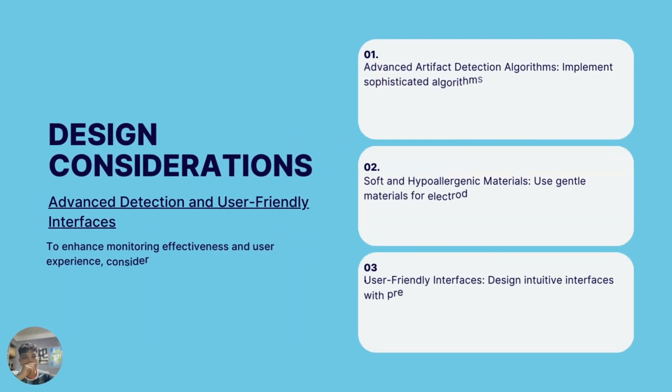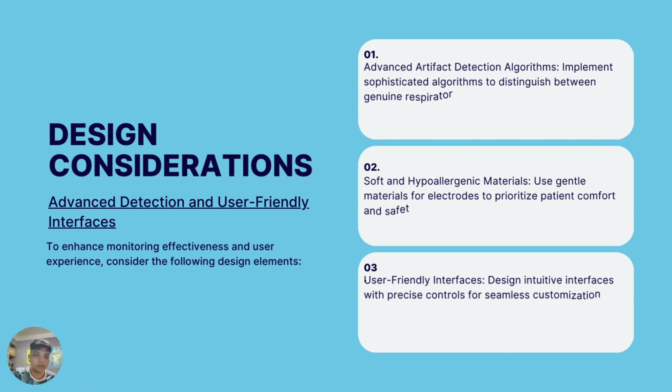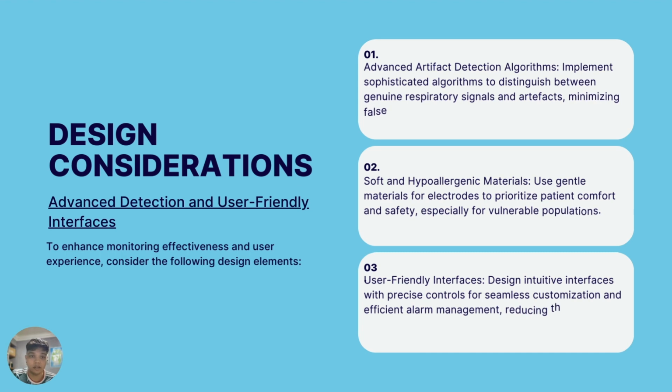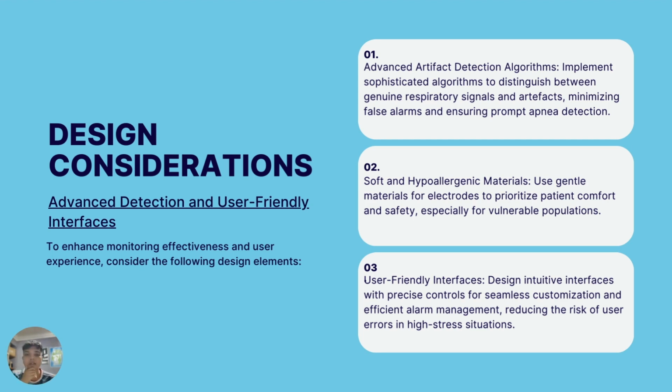Next, what are some design considerations? First off, designing apnea monitoring systems with advanced artifact detection algorithms is fundamental to ensuring accurate and reliable detection of respiratory events. These algorithms play a critical role in differentiating between genuine respiratory signals and artifacts, thereby minimizing the risk of false alarms or missed apnea events. By refining these algorithms, manufacturers can significantly enhance the performance of monitoring systems, especially in environments where artifact interference is super common. Additionally, employing a soft hypoallergenic electrode is crucial